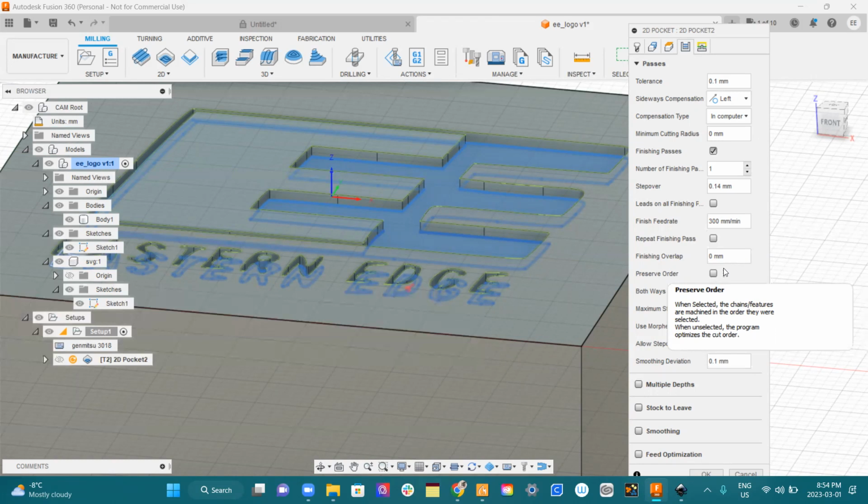So if I want it to be consistent, like if I'm machining metal and it's doing the surface of it, I can decide that I want it to look different ways. I can have it all cut the same direction, and then the top of it will have all these nice smooth lines on it. If it goes back and forth, it depends on your drill bit. If I cut one way, the drill bit is cutting into it, and if I cut back the other way, it's cutting against it. If I'm cutting a spiral, it matters which way my drill bit spins. So if I tell it to cut both ways on a spiral, it's going to change the surface and leave gouges, but it'll also do it faster. There are all these ridiculous things that you have to decide about. I don't care about any of them. Besides both ways is fast, please fast.